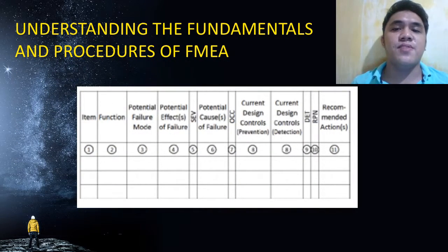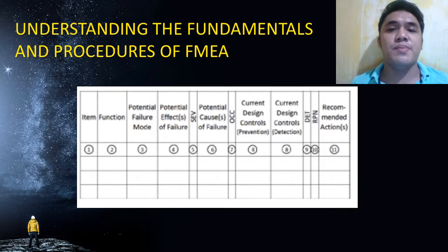So, understanding the fundamentals and procedures of FMEA. It is important to begin with an understanding of the basic definitions of FMEA. Time spent toward understanding the fundamental concepts and definitions of FMEA will shorten the time in meetings and help ensure high-quality results. There is no substitute for having a thorough knowledge and understanding of the FMEA definitions and concepts. So, Figure 1 is an example of a generic FMEA worksheet truncated after the recommended actions column. The numbers in the illustration correspond to the subsections in this paper. The definitions are presented in the sequence they are normally developed in the FMEA project.